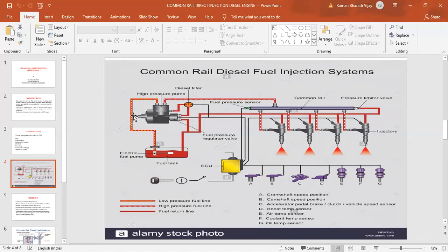So this is of low pressure, so fuel goes at low pressure, which is indicated by the red line with yellow dots. So fuel is transmitted to the gear pump at low pressure. You can see my cursor, it is of low pressure. And another thing, there's a gear pump. What is the working of the gear pump? It converts low pressure fuel to high pressure fuel. So this low pressure fuel is converted into high pressure fuel, and this high pressure fuel is getting away.